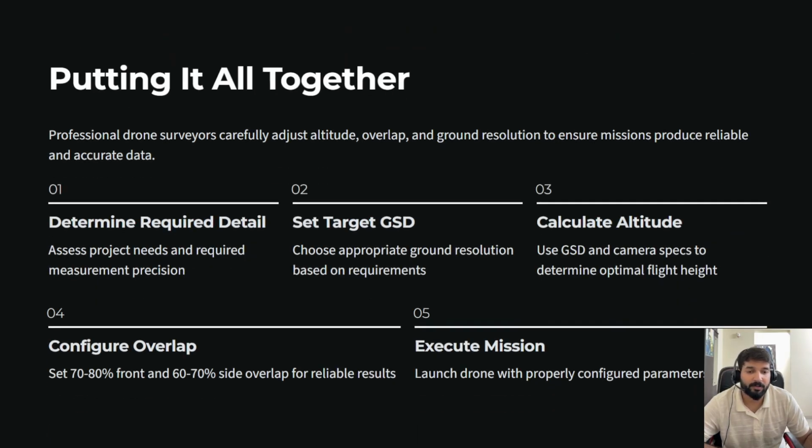Professional drone surveyors carefully adjust altitude, overlap, and ground resolution to ensure that their missions produce reliable and accurate data. By setting these parameters correctly, you can capture aerial imagery that is suitable for generating orthomosaic maps, terrain models, and detailed survey measurements.